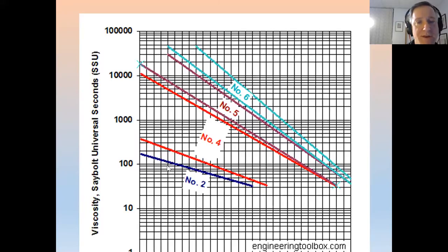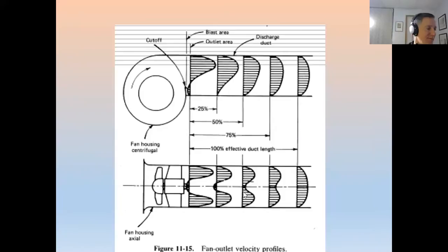So you can get this data from different sources. Viscosity is usually a function of temperature. And in a type of fluid called non-Newtonian fluids that we'll look at next class, viscosity is also affected by how fast it flows, or the shear rate, or pumping speed. That's kind of funky, and that really gives you deep insights into fluid dynamics.